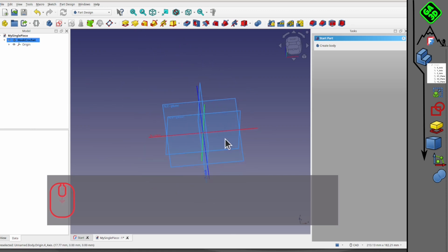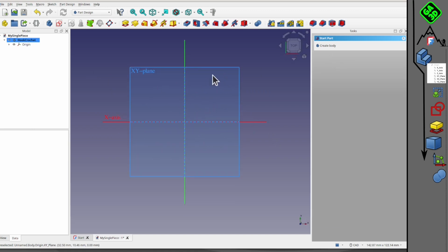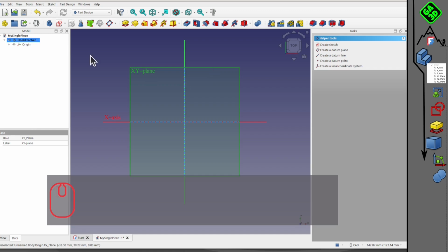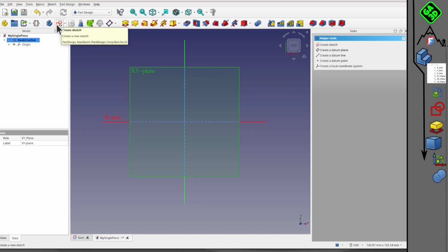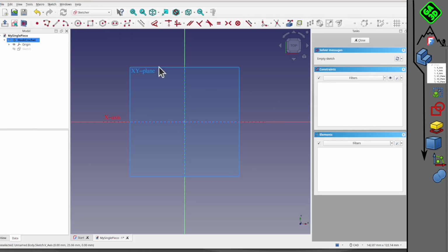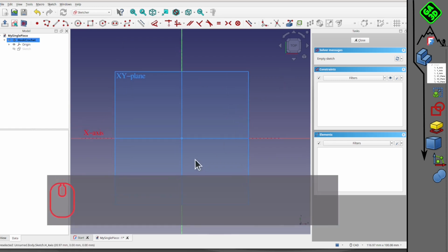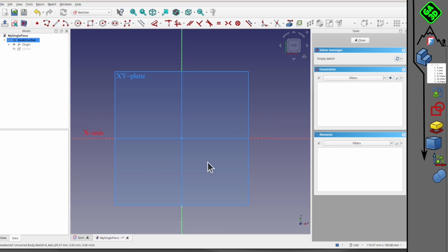There are plenty of tools, lots of things to learn about this workbench. We're not going to get lost in the details. The only thing I'm going to tell you is that here you have the construction elements, and then the constraints. After that, there are a few other specific things we'll see later. To draw this little hook that we could potentially 3D print, I'm going to use almost one tool, the polyline, so we just click on it. And then we'll draw on the fly, a little bit in proportion, as we imagine this hook.